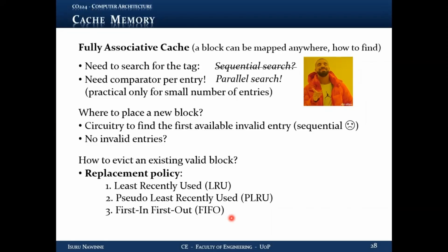But because the controller is very simple, in things like these embedded computing systems, embedded computers, when you add a cache memory, usually you go for FIFO policy as the replacement policy, because it makes the controller simpler, less hardware, less costly, less power consumption, and all that come with that. So a lot of different design decisions behind these choices, right? So the ideal one is least recently used.